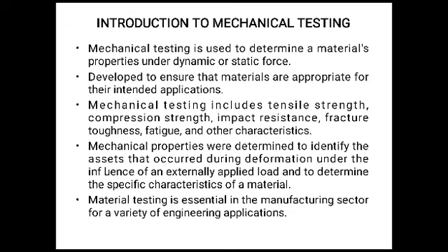Mechanical testing includes tensile strength, compression strength, impact resistance, fracture toughness, fatigue, etc. Mechanical tests are performed to determine the specific characteristics of a material and to identify the effects that occur during deformation under the influence of an externally applied load.